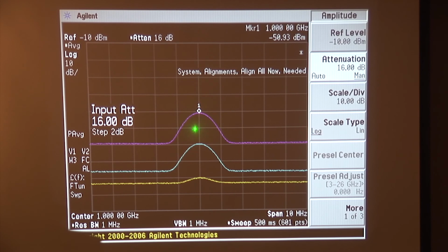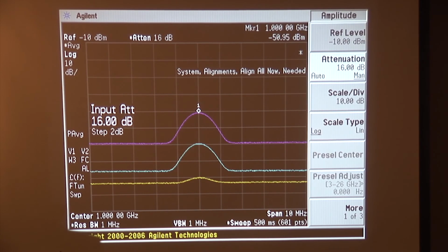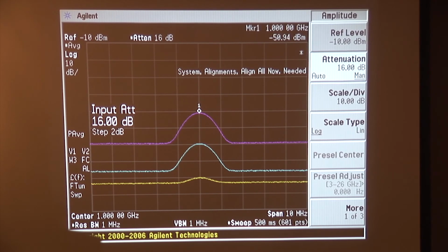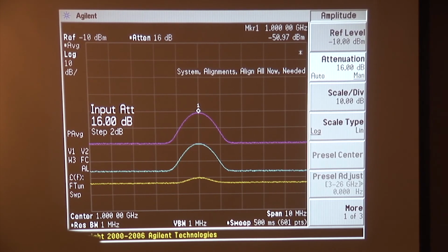But what you try to do is get the lowest possible noise figure, at least a noise figure that's low enough to meet the need of your application or your sponsor or your research, with only enough gain to overdrive the noise figure of the measurement system or the radio receiver, but you really don't need any more gain than that. That's really what the whole thing finally comes down to. And now we know how to do it.